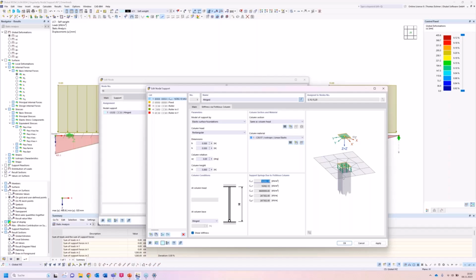As for a point load, in general, there's almost never like a needle holding a slab. It's almost always a column with a size. Mostly, I think the minimum size would be 18 centimeters by 18 centimeters. For Germany, you almost never go below 22 times 22, I guess. So we can also just take this into account.